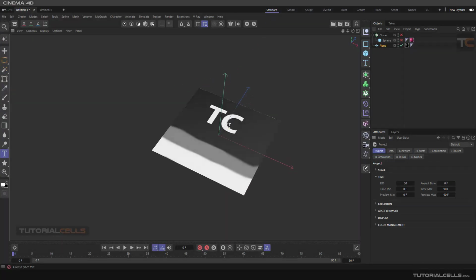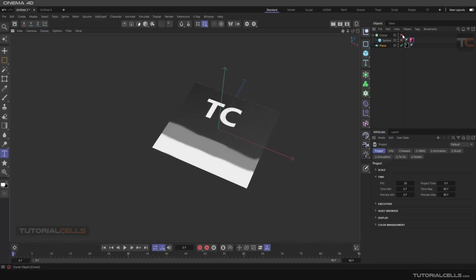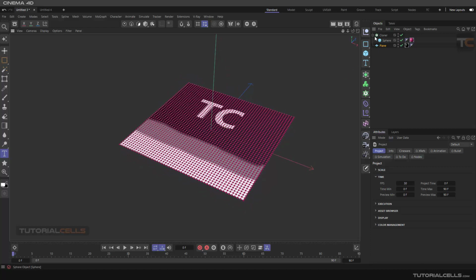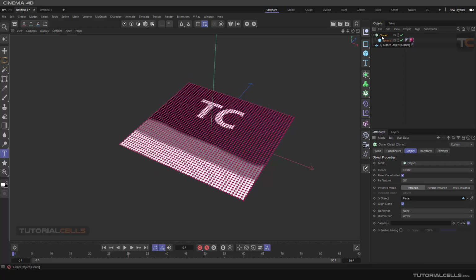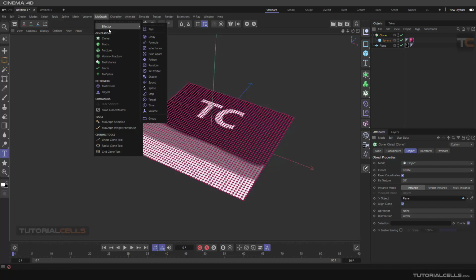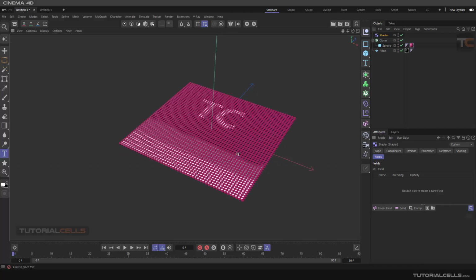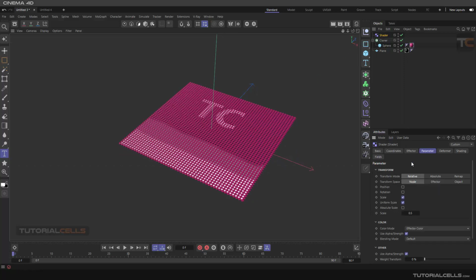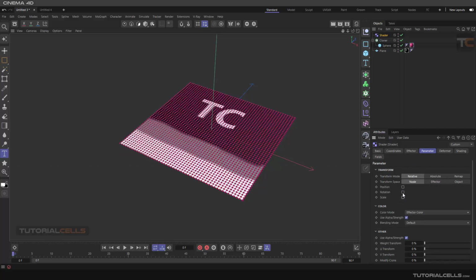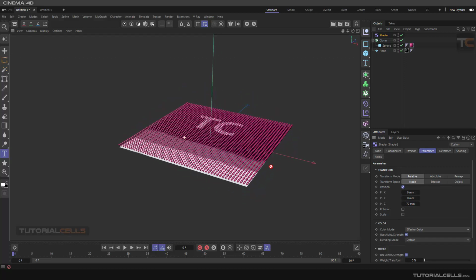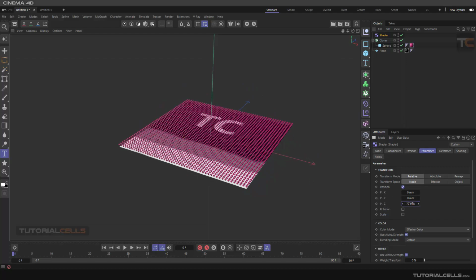And we want to use this texture as a shader for the cloner. Okay, this is our cloner. And we want to use that shader to bring them up. Okay, so in a cloner, we directly use effector, shader. Okay, as you can see, I think it changed the scale of that in the parameter. Yeah, it's a scale. For better seeing that, I use a position, for example, in this direction. Nice, it's bringing completely up.